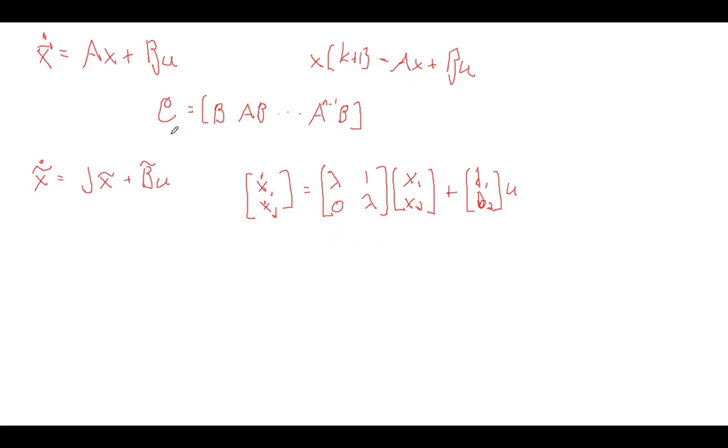And then I'm going to solve this controllability matrix explicitly. Okay, so first we're going to basically say the controllability matrix is B and AB, since I have to go up to the n minus 1 power. So I'm going to have to compute AB. Let's just compute that really quickly.